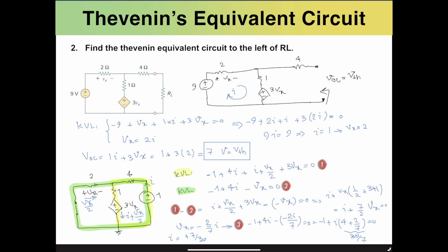No, plus 70 divided. So essentially I would be equal to 7 divided by 30. From this equation, I equals 7 divided by 30. And essentially, once I is known, we can find out what R Thevenin is, because R Thevenin is simply the inversion of 1 over I, which in this case is simply 30 divided by 7.